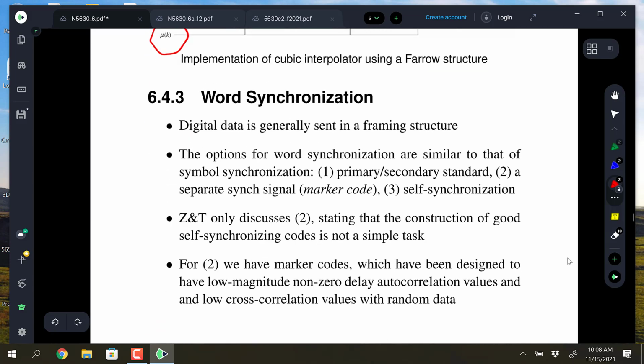Does that symbol synchronization, or do any of these deal with the four Ys, phase ambiguity in QPSK? No, they don't, so it'll come out with an ambiguity error. Right, I guess that's what word synchronization does. Yeah, or we could have differential encoding, and that could help too, and that's why we talked about that. But yeah, word synchronization will help with that.